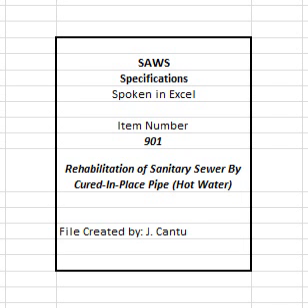C. Protection of manhole/structures: install all pulleys, rollers, bumpers, alignment control devices and other equipment required to protect existing manhole/structures, and to protect the pipe from damage during installation. Lubrication may be used as recommended by the manufacturer. Under no circumstances will the liners be stressed beyond their elastic limit. D. Do not allow sand, debris, or runoff to enter sewer system.